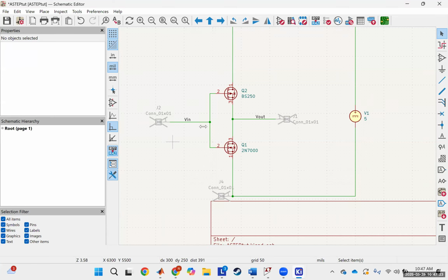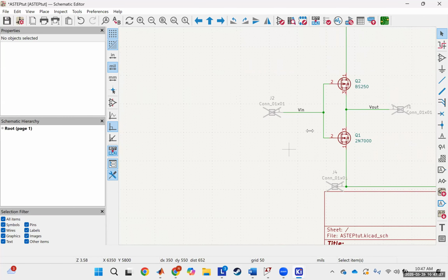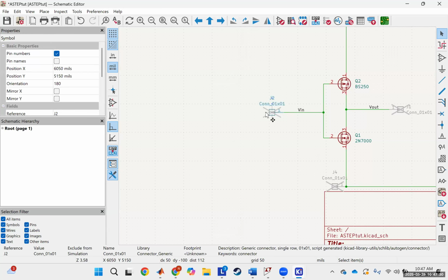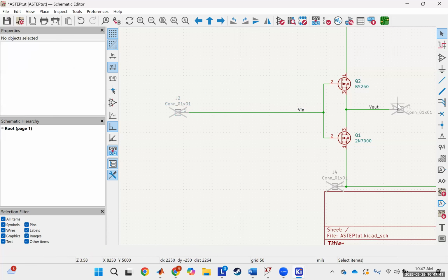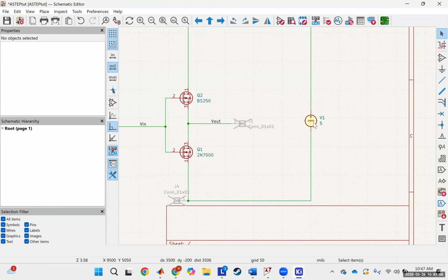Okay, next we'll need to put in our input signal. You can drag components if you just select them, the same way we did when we were going in properties. Click and drag your input over. You want to give yourself some room to put in our input signal source, a V pulse, because it's going to have a really long SPICE parameter line that's going to look a little bit messy if you don't give yourself some room. So this is going to be a source similar to this over here.